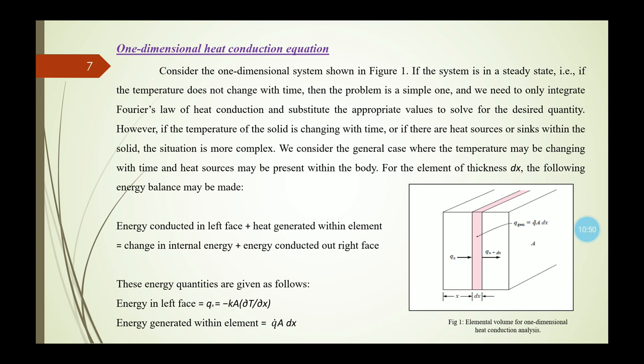Now let us discuss the one-dimensional heat conduction equation. There is a diagram given, that is the elemental volume for one-dimensional heat conduction analysis that we have considered. Now if the system is in a steady state, that is, if the temperature does not change in time, this is the concept of the steady state where the temperature does not change with time. Then the problem is not very complex and we only need to integrate Fourier's law of heat conduction.